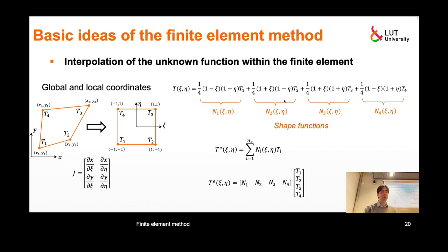So these shape functions, they are known. This is part of characteristics of my finite element approach. I assume certain type of shape functions. I know them. I can do with them anything because I know them explicitly. They are relatively simple. It will be a little bit more complicated if you wanted to use quadratic approximation, but the idea is still the same. So I'm using linear interpolation in this example.